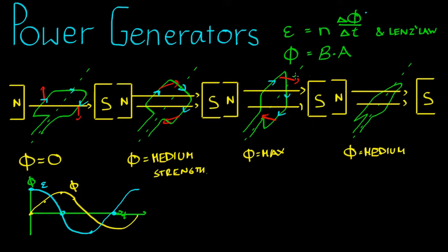The really interesting thing occurs here. As the loop turns over, remember we said this wire here becomes this wire here, it sort of pushes over like that. Well, the amount of flux through the loop is decreasing, because here it was full on perpendicular, we collected all those butterflies or all those magnetic field lines, but here it's collecting only a few.